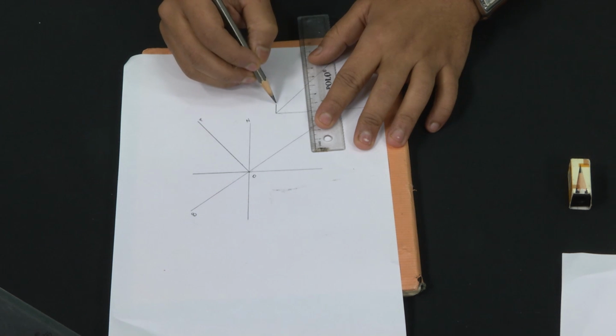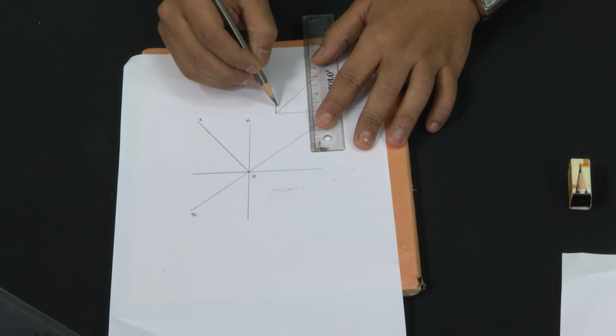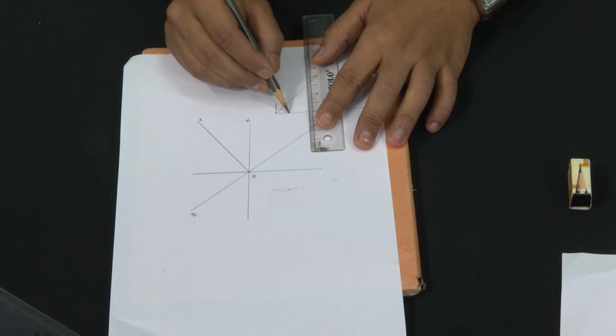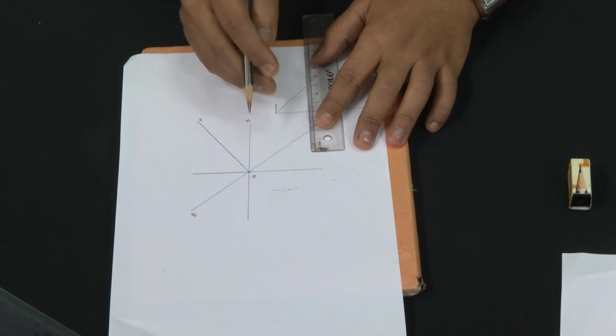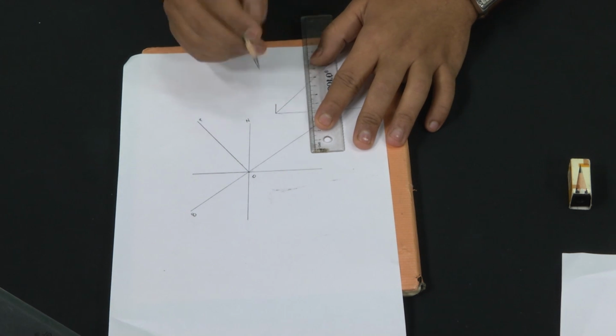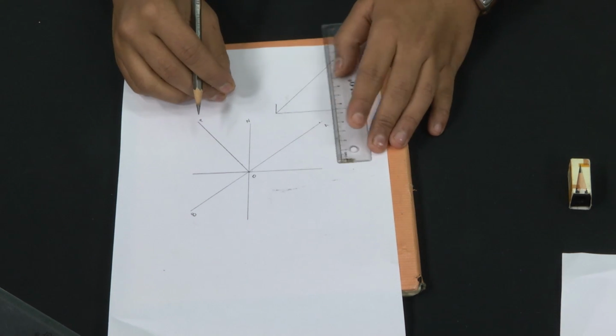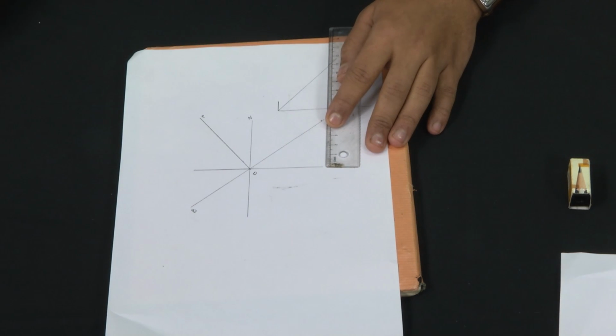horizontal line from this 100 meters, it will clearly intersect the dip line which I have drawn, and then if I project the point I obtained on the dip line perpendicular to the horizontal line and parallel to the vertical line, I will obtain a point on the horizontal line. So, clearly the distance between this and the point I obtain will be my horizontal separation in plan view. So, we will do the task right now.